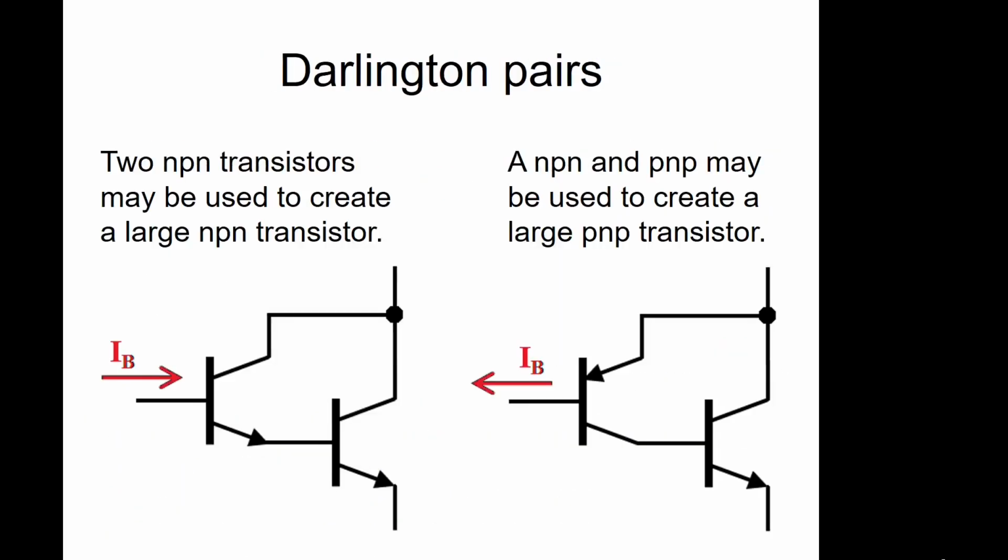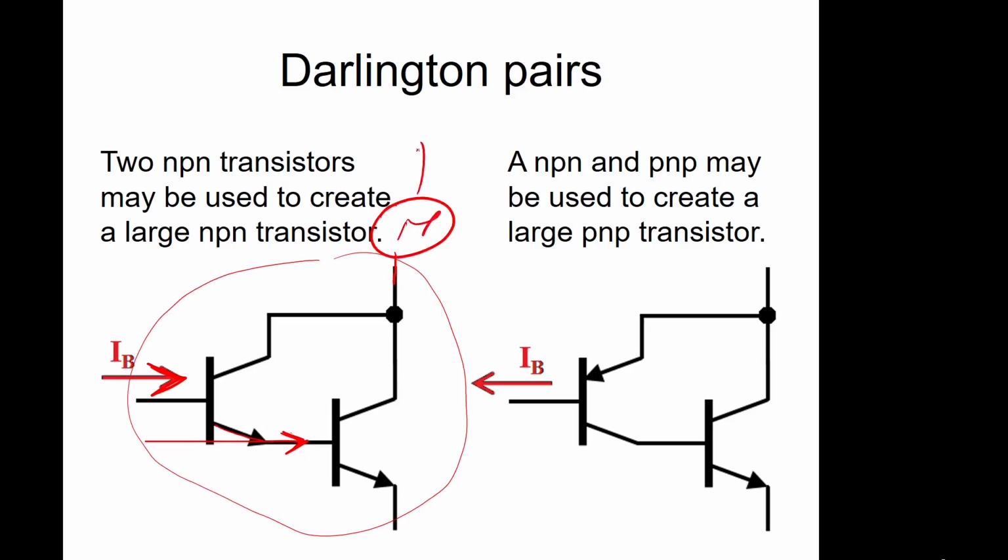Power transistors are two transistors connected together. So you can see this is an NPN arrangement here. And what we have is a small base current coming in here. This then drives a larger emitter current here, which then forms the current going into the base of a second transistor. So our motor might be here, and the current flowing is now significantly larger because we're getting two lots of amplification through the system.